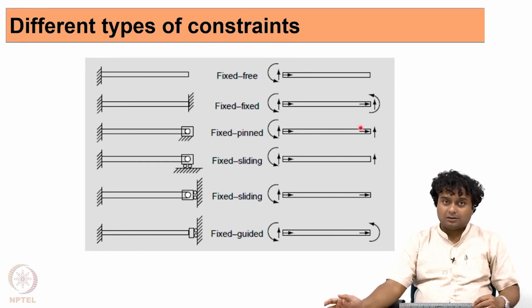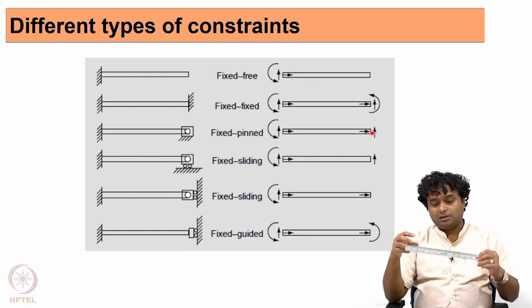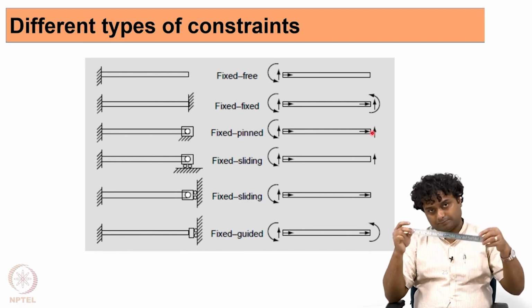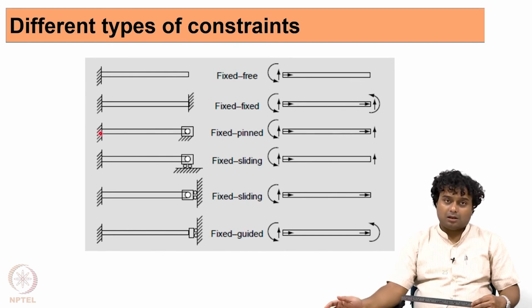While the motion is restricted, only then is a reaction force present, right. So this end will have horizontal and vertical reaction forces, but the moment will not be there, because it is able to rotate with respect to this pin point. Okay. But the other end is anyway totally fixed, so it will have all the forces and also the moment.